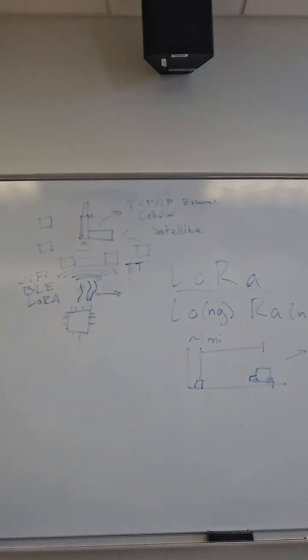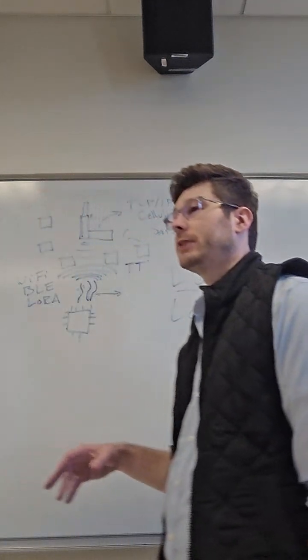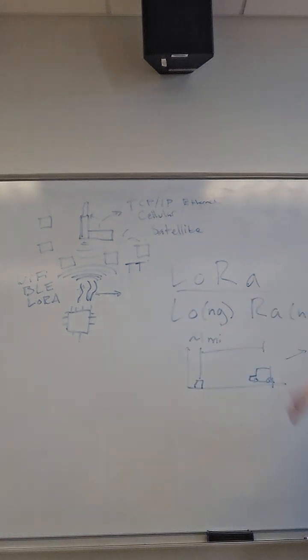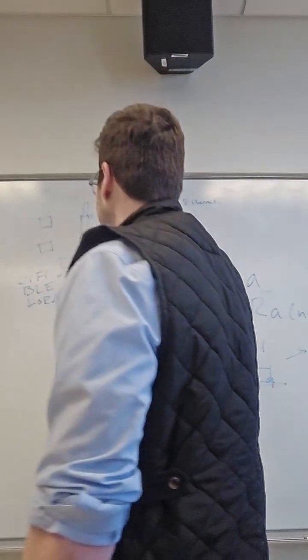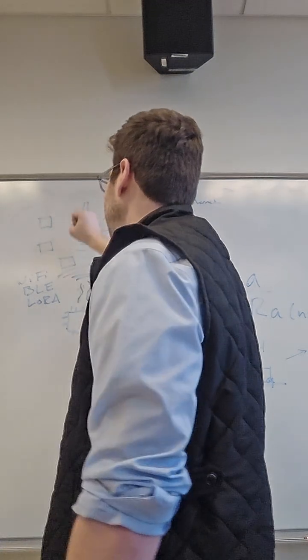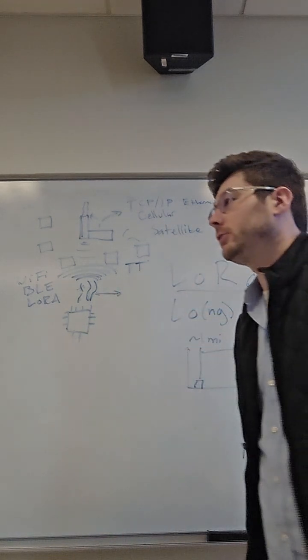These would also be the devices that would send out information. So if our end device was a motor and we wanted to turn that motor on and off or set it to a certain speed or whatever, it would be attached to our network and it would have a unique address. And we would go, hey, motor AB619, turn on, right? And then it would get the packet. It would go through this whole chain, the rest of which I'll explain in a second. But at some point, our gateway would broadcast the signal that was meant for our end device, whatever address I just said, that it would be listening for and could turn on or off or do whatever we tell it to do.